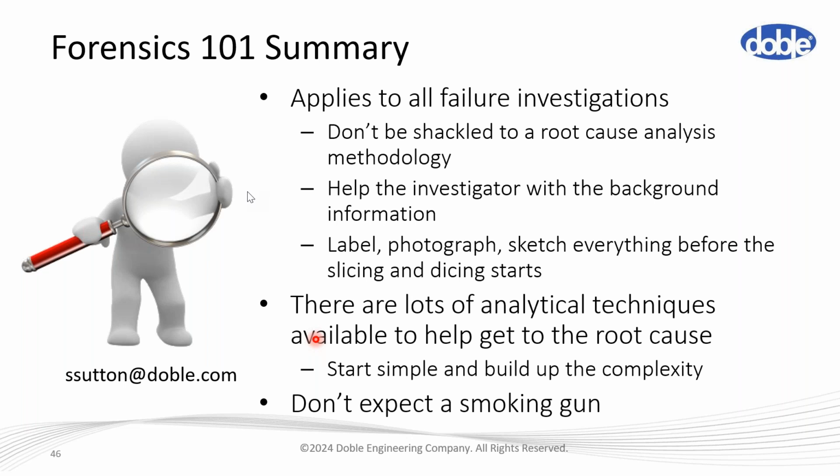So they would go to a higher voltage than the IEEE 400 document would recommend, the crew would be in the area for a week or two, and then if they had subsequent failures, they were in the area, they had the spare parts with them, and they would do the repair. So that was kind of culling the weakest in the population.